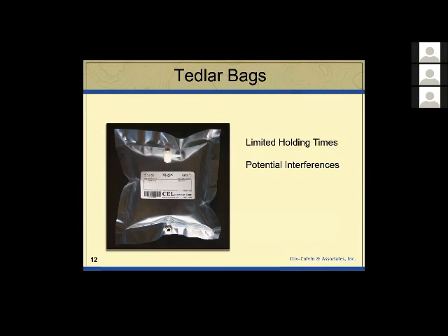A lot of people like Tedlar bags. They're cheap and you can throw them away when you're done, so there's no risk of cross-contamination, but they do have limited holding times, typically 2 days, and they have potential interferences, which is to say they contribute some VOCs and take away others. I've used them to transfer gases sometimes, and I might measure field parameters out of them, but I'm not a fan myself, but they're certainly usable too.